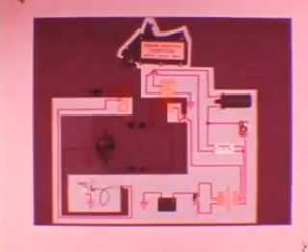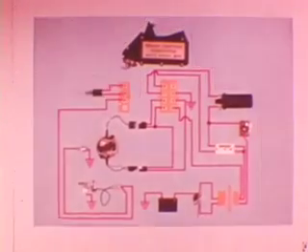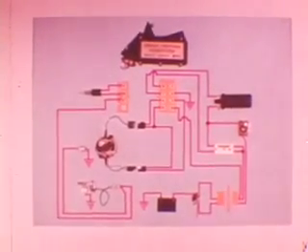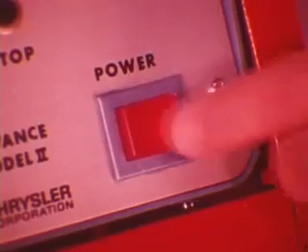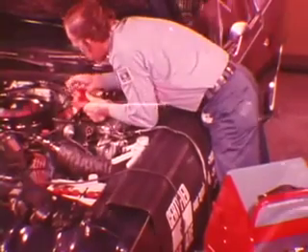And that all components in the primary ignition circuit are functioning properly. The coil, the starter relay, both sides of the ballast resistor, the ignition switch, carburetor switch, coolant temperature switch, complete distributor circuit, throttle position transducer, and vacuum transducer. Turn off the analyzer and ignition before disconnecting any of the leads. That leaves only the high voltage circuit in question, and that is easily checked by cranking and looking for a spark.